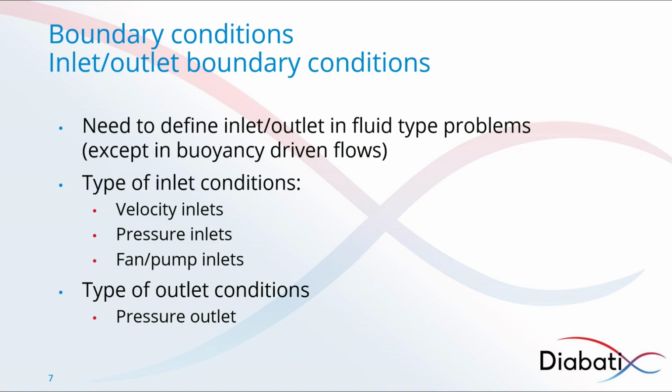The fixed flow rate inlet boundary is often combined with a pressure outlet boundary, which is also the case for the cooling jacket as we have seen on the platform before. And with the pressure outlet condition, you basically specify the total pressure at the outlet. So when you have, for example, an isothermal simulation and the inlet and outlet boundary condition are set, the CFD code will be able to solve for the flow field in the entire domain.